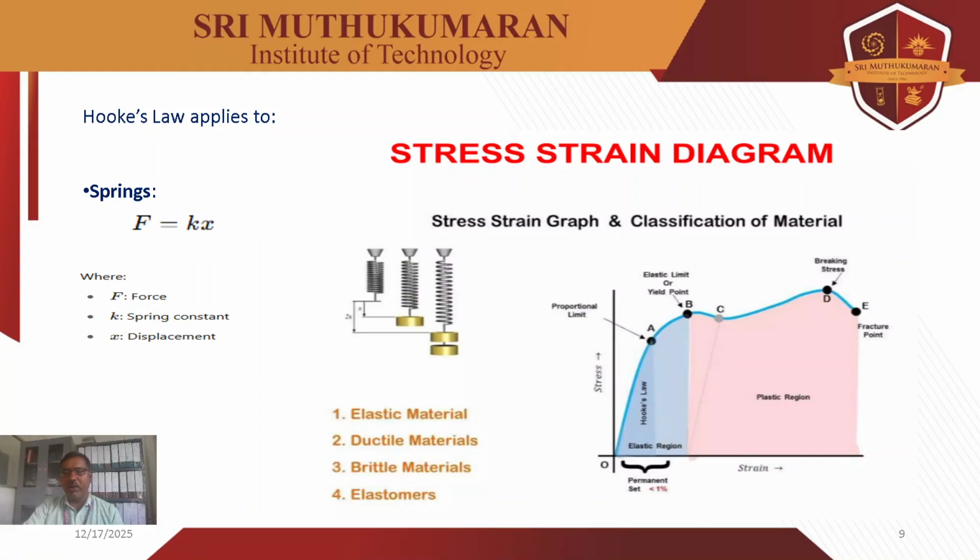There are two yield points: one is the upper yield point, the other is the lower yield point. Next, the ultimate stress. The ultimate strength is the B point on the x-y graph, where the y-axis is the stress. The top of this vertical line is the ultimate stress point. It represents the maximum stress that a material can endure before failure. Beyond this point, failure occurs.